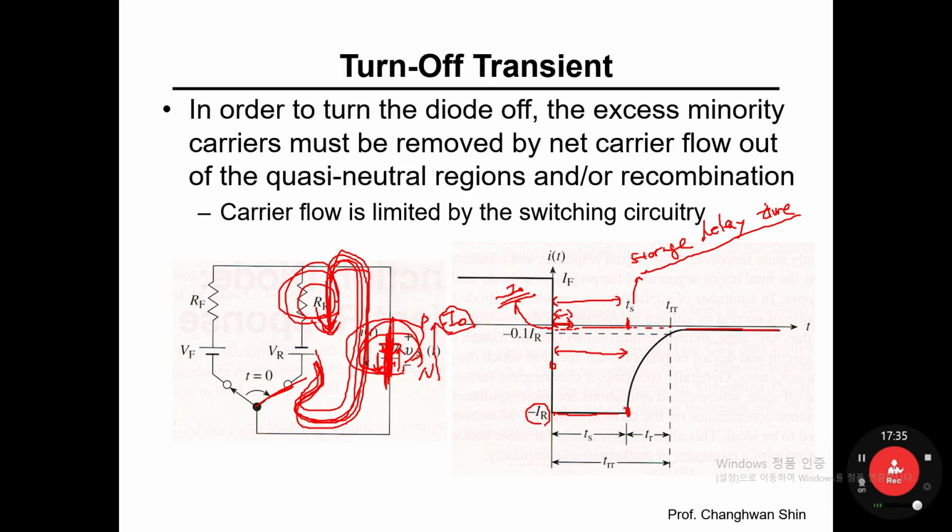So now the stored excess electrons and holes are removed, and the current value should asymptotically approach the saturation current of the PN diode. Now this R_R is nothing. I mean, the effective resistance value of this diode is much higher than the R_R value. So the whole current throughout this loop is fully governed by the effective resistance of the diode.